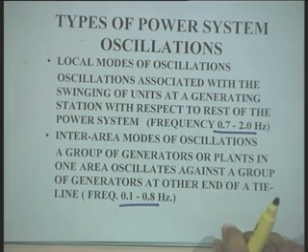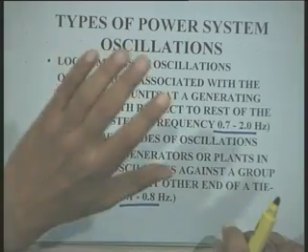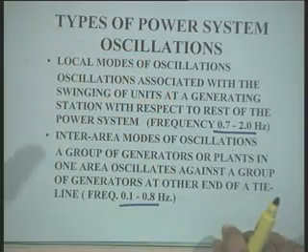It depends upon the system operating condition and system parameters. And therefore, as the system operating condition changes, the phase lag characteristic of the system also changes, and therefore, the design of the phase compensator so that it meets the requirement over a wide range of frequency is a real challenge.